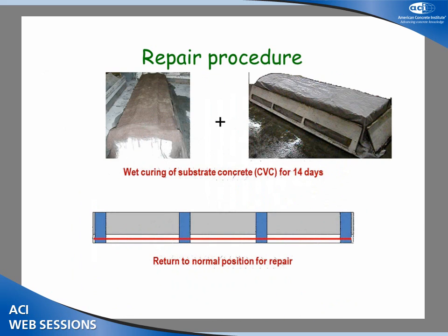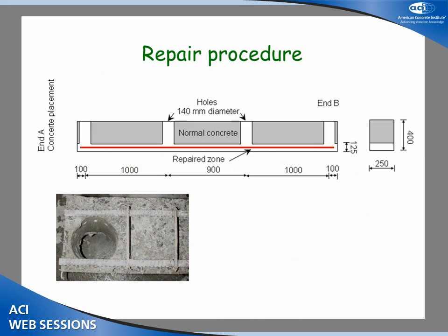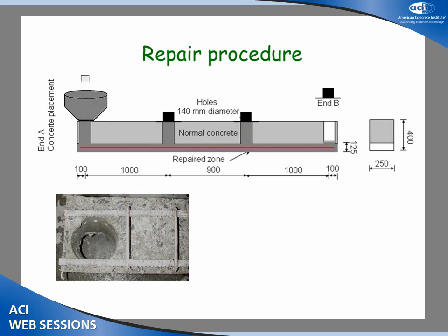And that was cured properly. And when it was time to cast it, we had pre-inserted PVC sections, like you see over here, 4 inches. And we introduced the SCC by gravity, ensuring continuous placement without any stopping. And as the concrete came up from the different observation holes, we just plugged them, and that's how we had this 125 millimeter tension zone concreted. So the question was, is this repair section going to behave similarly to a monolithically cast section, whether with fibers or without fibers?